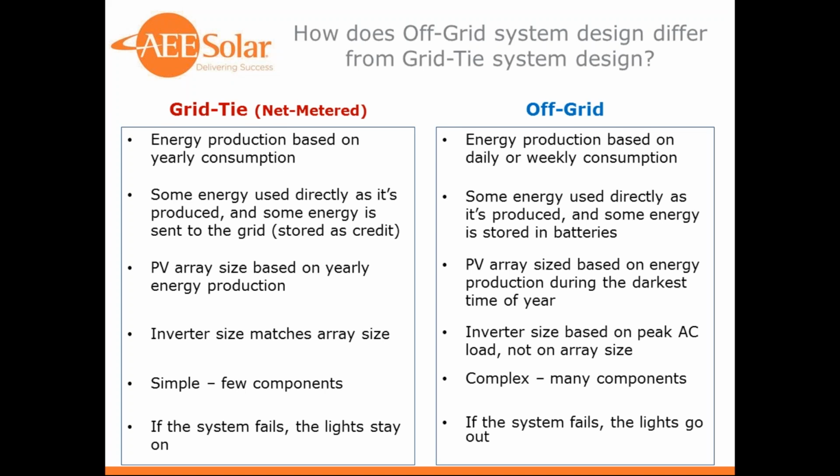The array size is based on producing enough energy for the day or the week, but the inverter is used to run loads directly and is not really part of that energy production cycle. And I'll explain that a little more later.